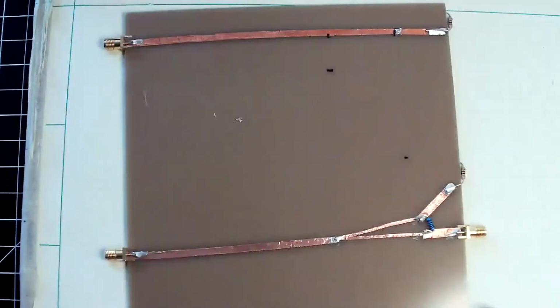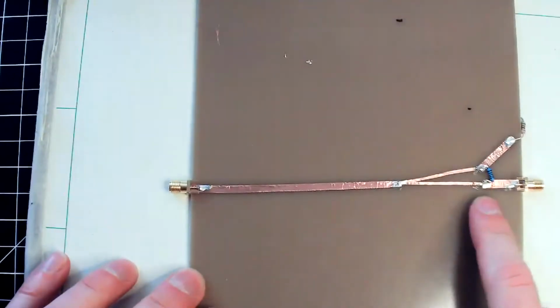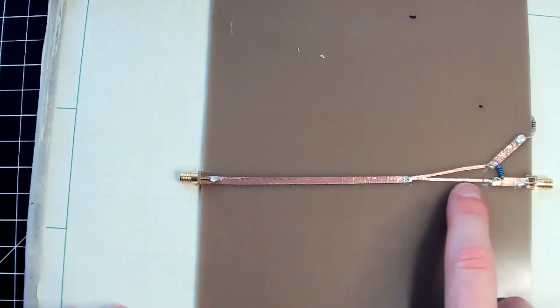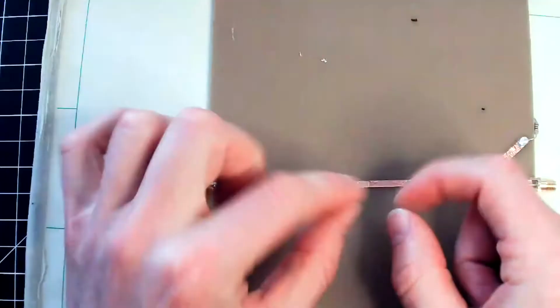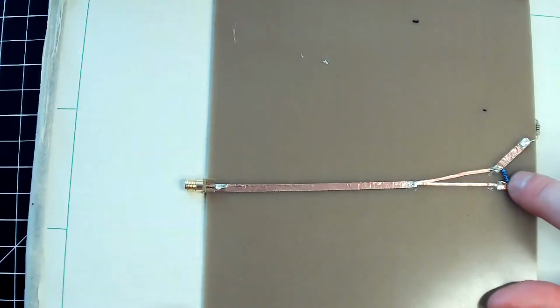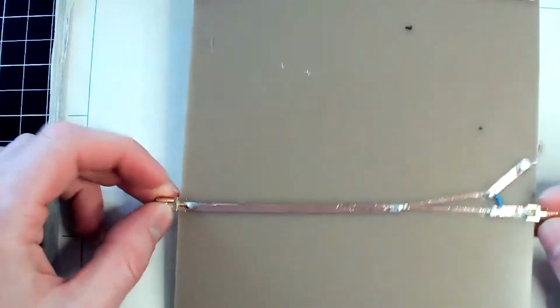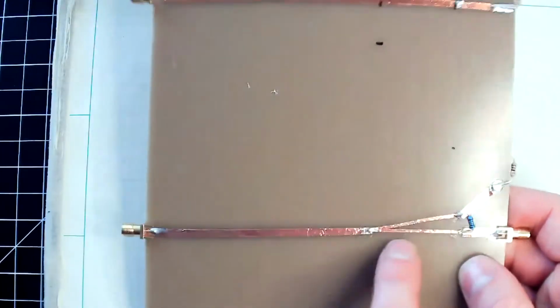Also, fun fact, I made a very pitiful attempt to put one of these together yesterday. It didn't work so well, but this is kind of how it should look. So there's my 50 ohm line. There's my, it's really hard to get exactly 1.5 millimeters with your bare fingers on this stuff. So I tried, and then I put a little 100 ohm resistor here. There's a 50, and then I would put a little 50 ohm and tried to measure return loss on this. It was kind of like this flat minus 10 dB everywhere. It was kind of hideous. So my hunch is just this did not work out so well when I tried to put that together.